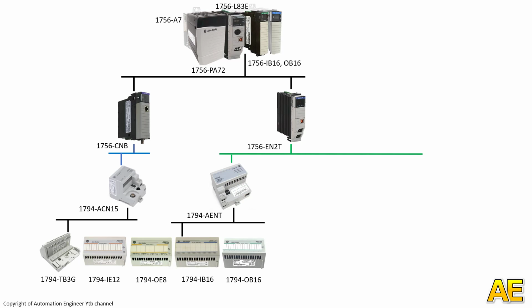Next, for controlling the VSD and other Ethernet devices, we need more Ethernet ports. So we use an Ethernet switch. That switch you can also get supplied from Rockwell Automation. We can use the Stratix model 1783-US.